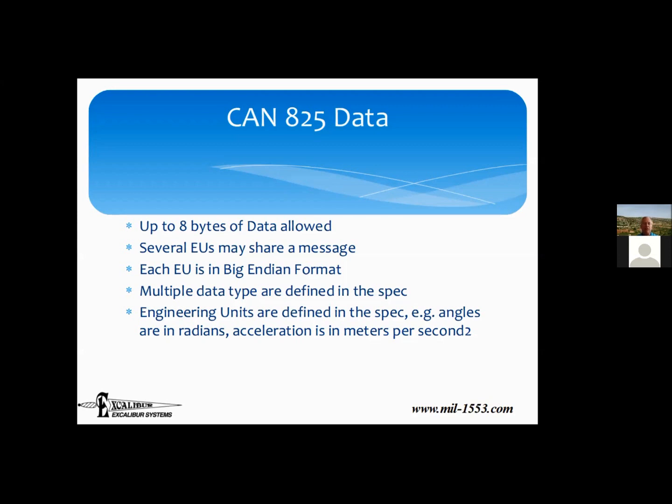Actually, no, it tells you to send it in radians. Angles can be done in a number of different ways. One way is degrees, minutes, seconds. You're familiar with 90-degree angles, so that's a degree. Radians is another method of doing it. There's another method called semicircles. MIL-STD-1553 tends to use semicircles. ARINC-429 tends to use angles. CAN Bus uses radians. Acceleration, meters per second.